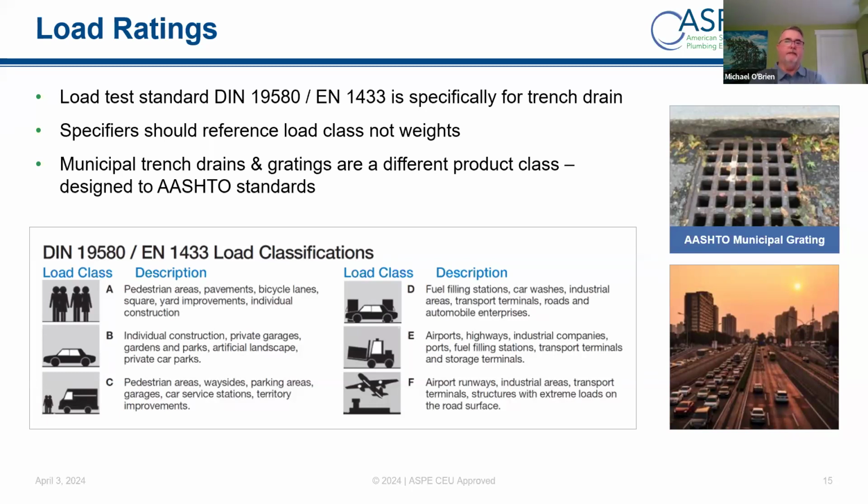The one thing to consider, though, if forklifts are involved, is where the forklift's turning wheels will be, because if they're sitting on a grate, they're putting a lot of twisting on that, and they can cause some issues with the longevity of the grate and also the channel system.